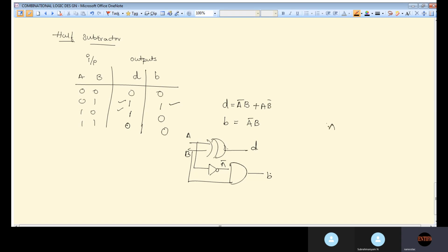You can go with AOI logic, and you can implement using NAND and using NOR gates. Look, for you guys NAND and NOR implementation is very important for any circuit. Why? Because in real time we will be using universal gate logic only.